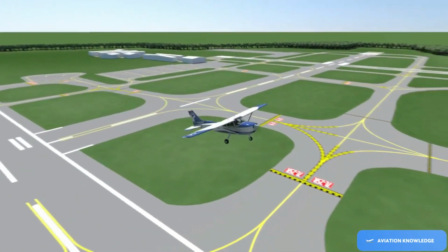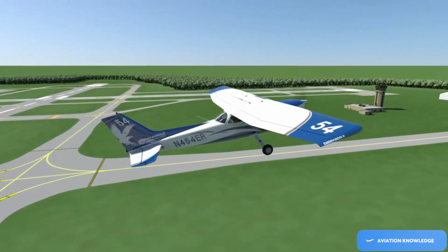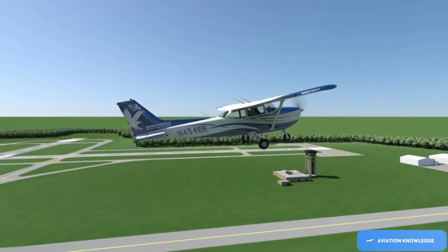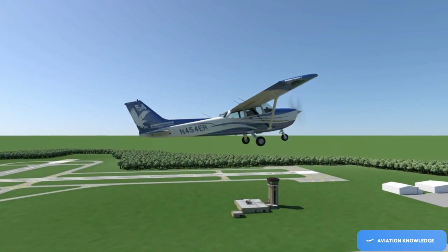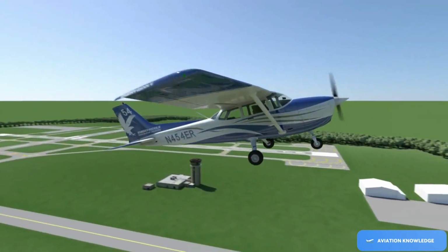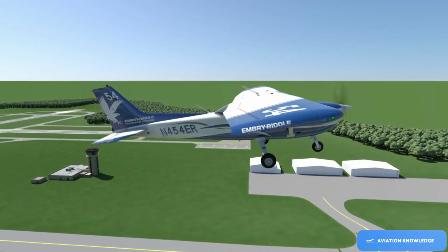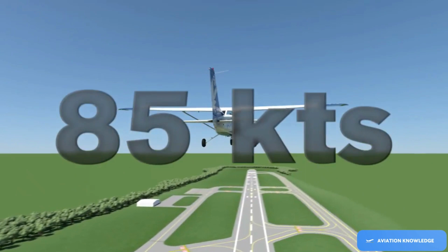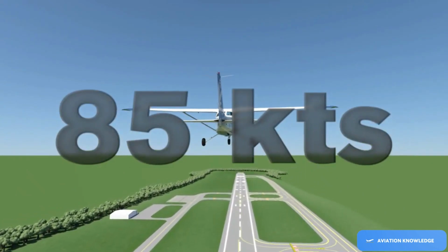When the aircraft is at least 200 feet above the ground, briefly lower the nose toward the horizon to ensure that there is no other traffic in your flight path. Once the area is deemed clear, resume the VY pitch attitude. At 500 feet AGL, lower the pitch to increase the airspeed and continue to climb, now at 85 knots, which is our cruise climb airspeed.